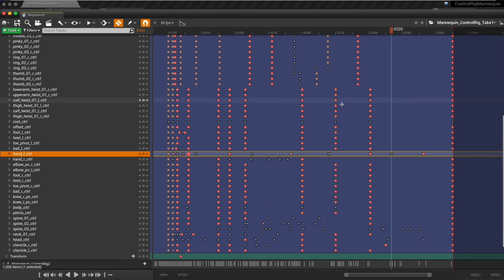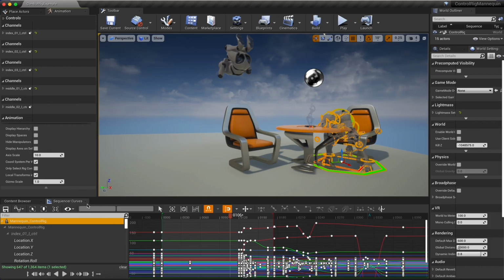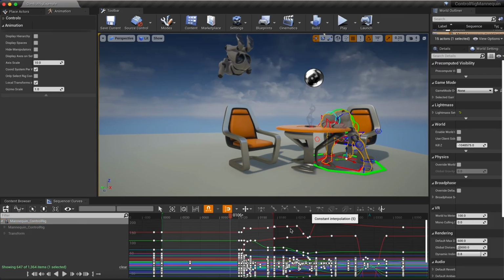The reason why we have some separate keyframes here but the animation looks very smooth is that we can open these sequencer curves, and you can see that for these curves I use a curve instead of a straight line, so it will not change suddenly but will automatically blend the start condition and the final condition to make it link smoothly, and it will not seem too strange for the final effect.